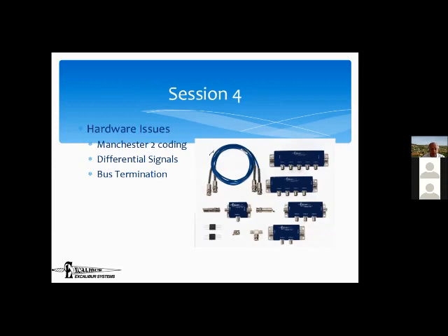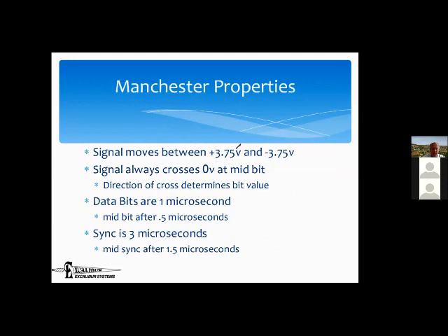Okay, so that handles the non-directly spec-related issues. And I want to talk about how you connect the bus, because we had a lot of experience with people connecting it incorrectly, and it's a very, very, very difficult problem to solve, because things will sometimes work and sometimes not, which are the worst kind of problems. I want to talk about differential signals and bus termination. So I'll see what each of these things mean.